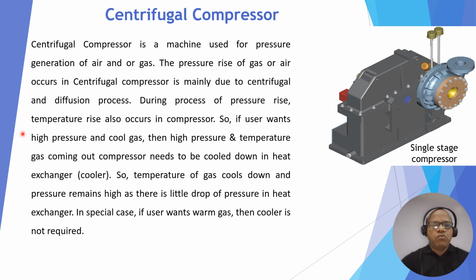So if the user wants high pressure and cool gas, then the high pressure and high temperature gas coming out from the compressor needs to be cooled down in a heat exchanger or cooler. Cooler is also sometimes called a heat exchanger. So the temperature of the gas cools down after the heat exchanger, and pressure remains almost the same because there is very little pressure drop in the heat exchanger. In a special case, if the user wants warm gas at high pressure, then a cooler is not required. So this is the basic purpose of centrifugal compression.